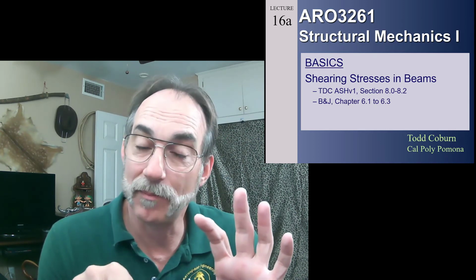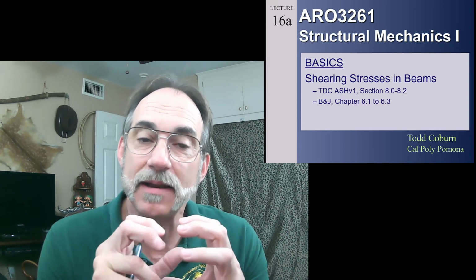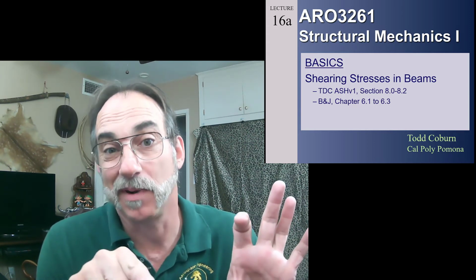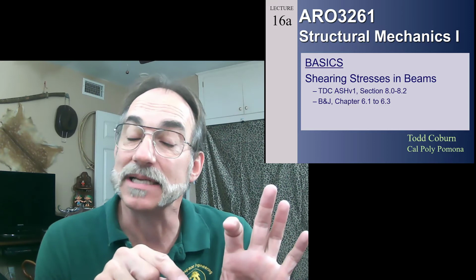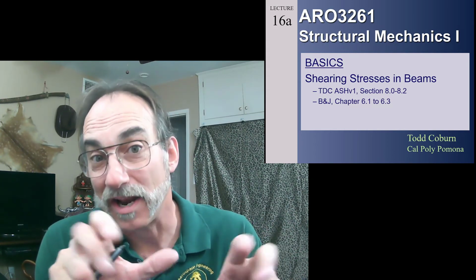That does happen to be close to true if we have a thin-walled member like an I-beam. But when we have any kind of structure with significant area other than the extremes, if it's not super thin, then what we'll get is a parabolic distribution of stress. Actually, there's always a parabolic distribution of shear stress, but sometimes the change in shear stress is so slight in that parabola that we can assume that it's P over A with not a huge loss of accuracy.